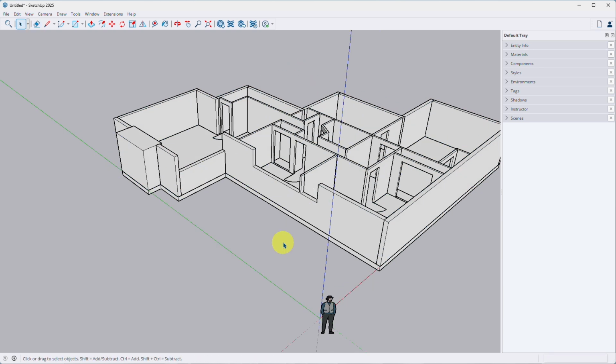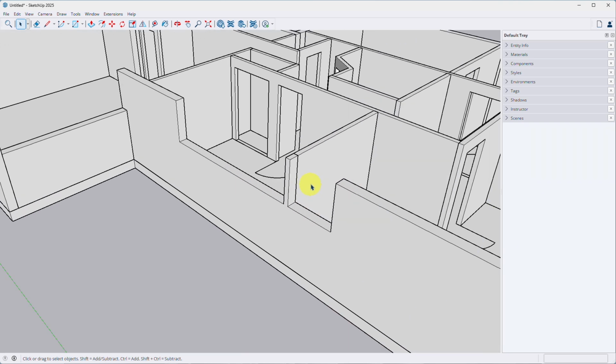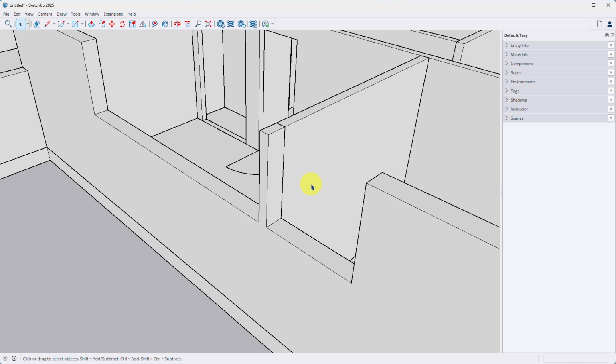There are many different styles of window and many ways of creating them in SketchUp. In this instance, we will create a very basic window. First, create a simple rectangle using the extents of the window opening as a guide. Then, use the Offset tool to create the thickness of the frame. Tap F for offset. Then, click and drag the perimeter inward and type 1 inch.